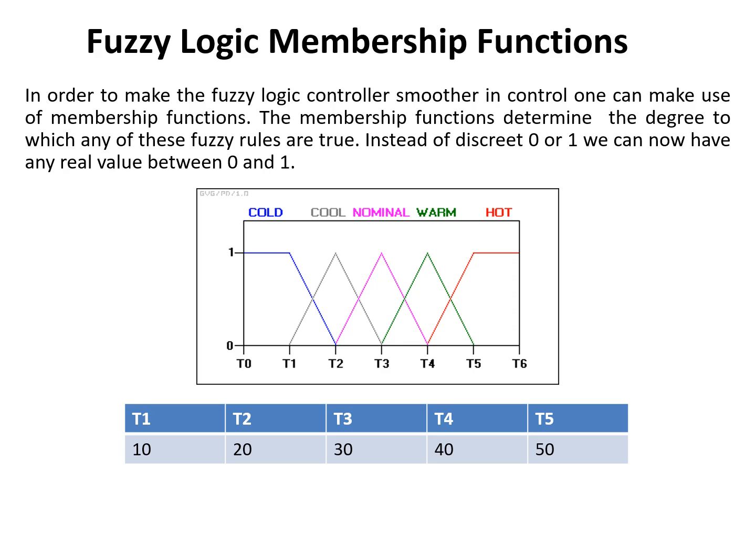But instead of being either cold or cool, we'll now say we have a membership between these two regimes, and the degree of membership indicates how much of the output is of a specific value. So for argument's sake, here we have the cold state, which has a membership of 1 and then drops down linearly until we get to the perfectly cool state. So this is where perfectly cool is. At the same time as the cold state decreases, the cool state increases until it reaches a maximum.